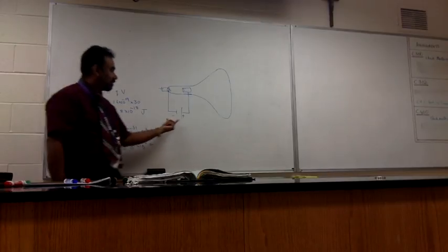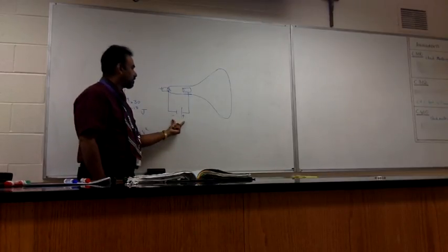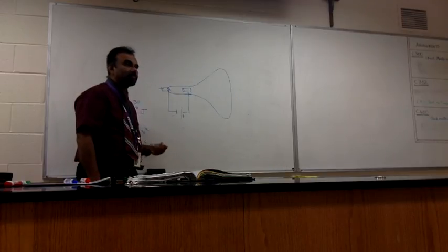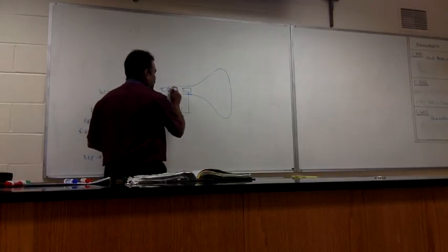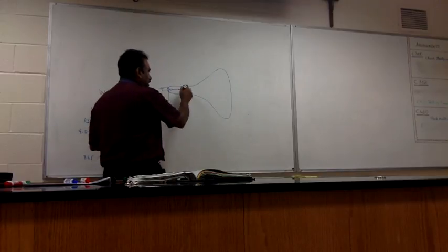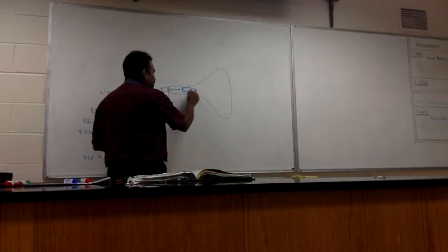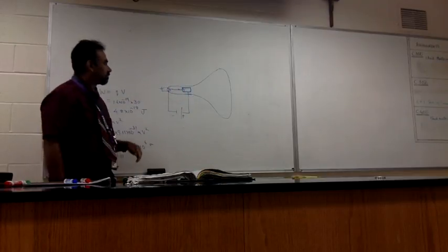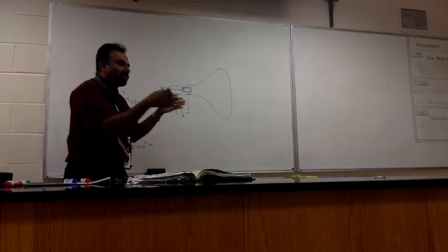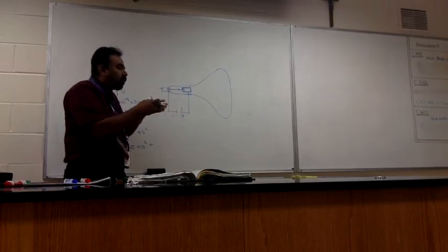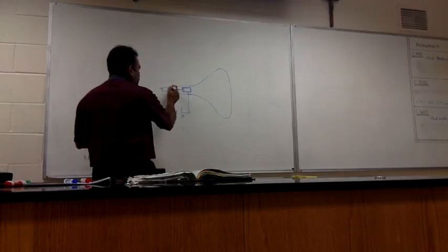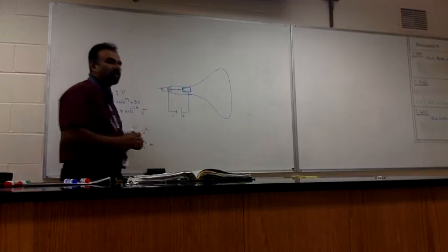Why such high potential difference? Because we want to accelerate that electron really well, to high speed. So when the electron comes out from here, it gets accelerated and goes through the middle of the cylindrical anode. It's actually focused through the middle. There's a different focusing mechanism, which makes it go through a certain region. So it comes out from here, and before it goes here, there are some grids over here. The grids are supposed to be used for brightness control.